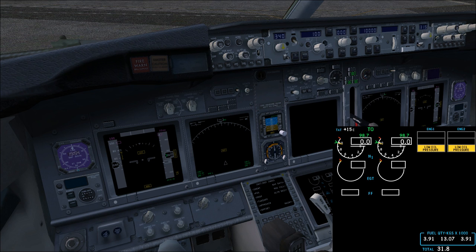This is the standard one, and it presents mainly primary engine indications, and also category 3 or autoland information in case you have an active fail-active autoland system. The iFly is not mounted with a fail-active system, so we have just engine information on this part.